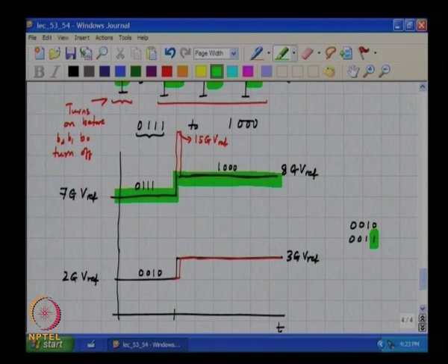They are very different, simply because when you go from 2 to 3, you get the ideal step plus, which is just delayed by a little bit, but when you go from 7 to 8, you see that there is a big spike, right, even though the change in the input code remains the same. The change in the code was 1 in both cases, however the change in the output waveform was very different depending on what code was there before you increased it by 1, alright.